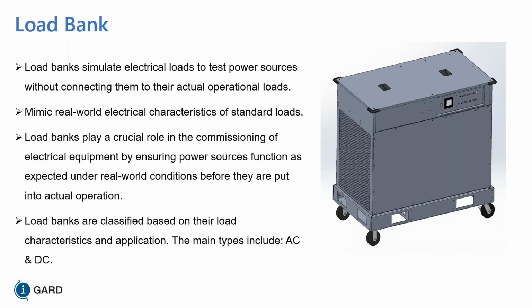Load banks play a crucial role in commissioning of electrical equipment and ensure power sources function as expected under real world conditions before they're put into service. So basically, you're going through the motions of a load and testing your source in all possible examples. So sudden drops in load, increases in load. How is your power source going to react to this? And some of the standards that we're looking at later actually look at this.